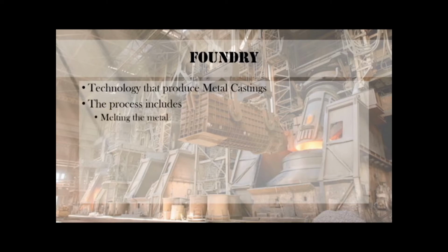First of all, we have to melt the metal in a furnace. Pour the molten metal into a mold. When the mold cools, the metal solidifies. Now, remove the casting from the mold. After removing the mold material, clean the casting.